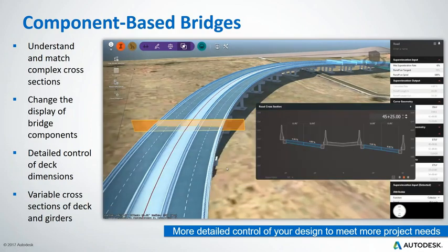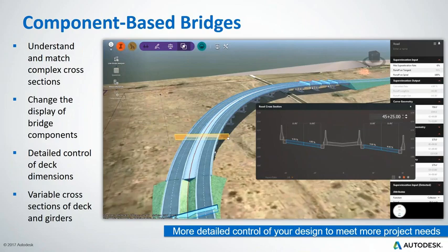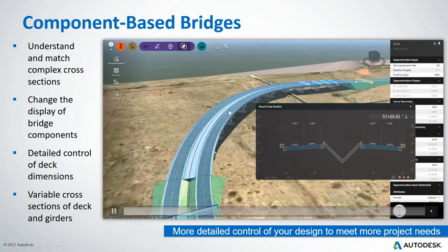You can replace those assemblies. You can actually check the cross section, and as you can see, it's very intelligent because it has actually detected that there should be a super elevation over that curve and created the super elevation depending on the design speed accordingly.